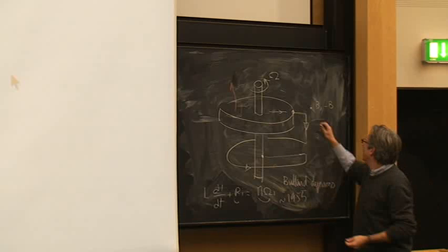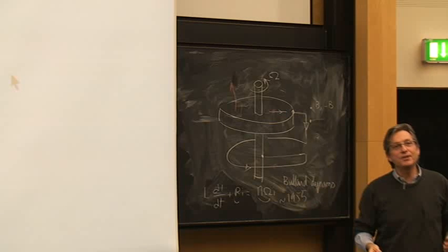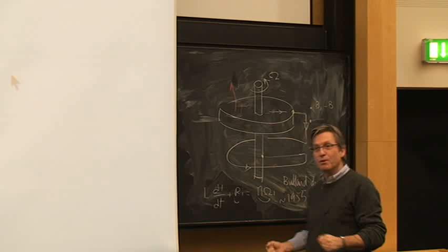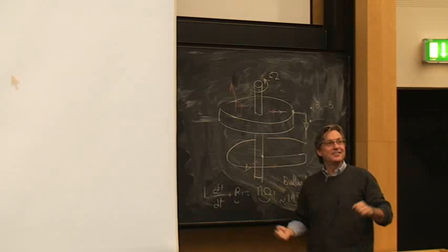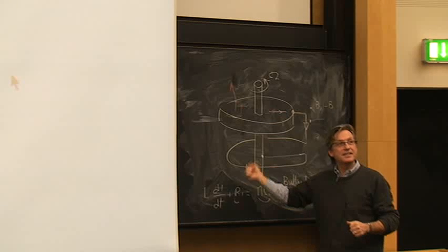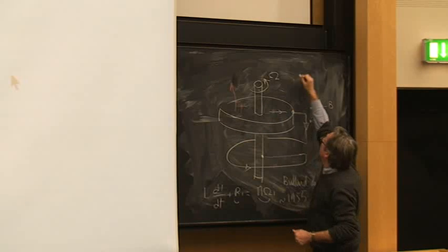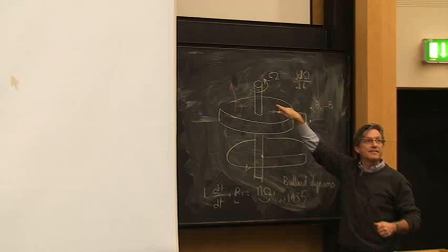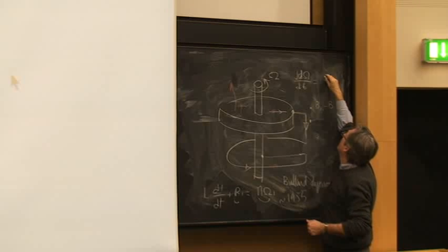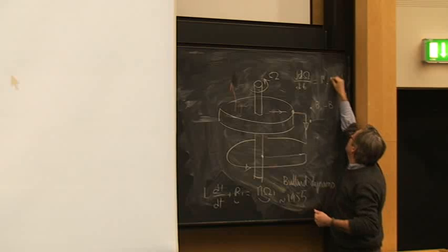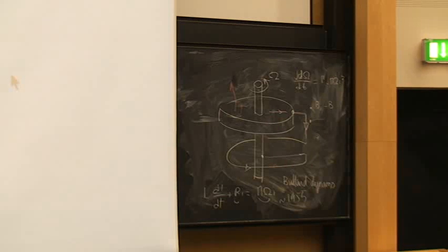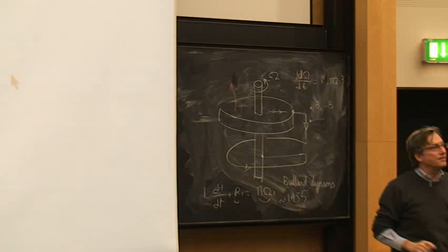What else? One question with which you can kill a first-year student is what happened to Lenz's law, saying that causes have to oppose, blah blah blah. Well, that's not in this equation. It's the mechanical equation that says T d omega/dt, which is how that thing moves, is the usual driving torque, but in that case it's minus M omega I squared. And the torque is always a braking torque, whether you're starting a dynamo or not starting a dynamo. It just depends that you have currents in there.